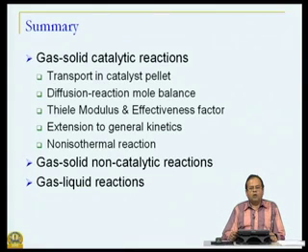While we can characterize the bulk flow by the diffusion coefficient, we have to worry about the diffusion coefficient of the Knudsen regime and the capillary flow and so on, and we tried to put all these together into what we call the effective diffusivity of a reactant in the catalyst.